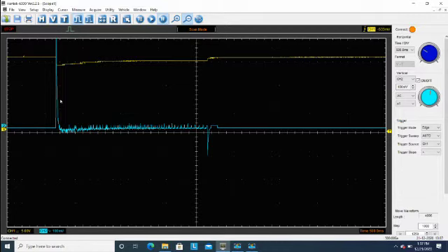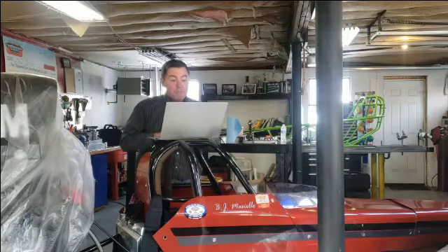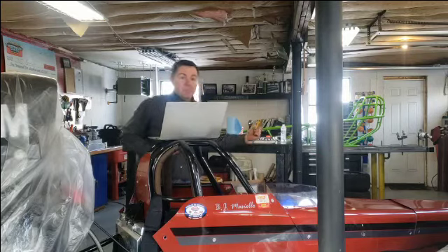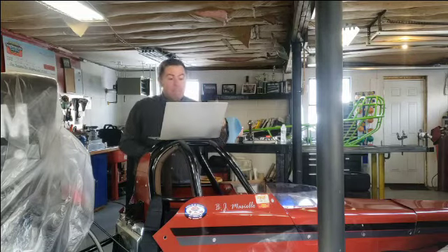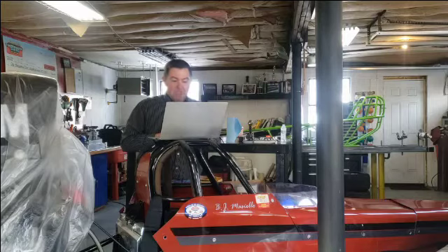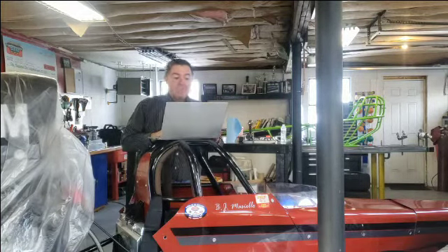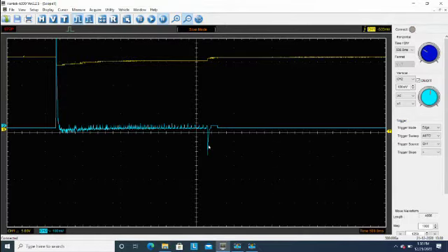And as this motor is coasting, what it's doing is producing current in the opposite direction. That electromotive force that we talked about, well, now that there's no potential towards the electric motor, what we have is voltage being generated by that electric motor in the opposite direction. And we see current flow happening because of that in the opposite direction. And that's why we see our negative line on our graph. Hopefully this helps you to better understand the concept of voltage and current.